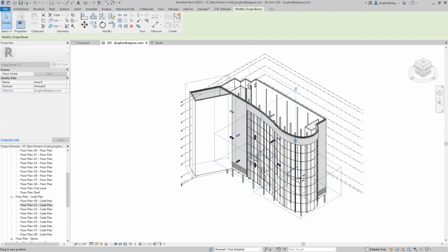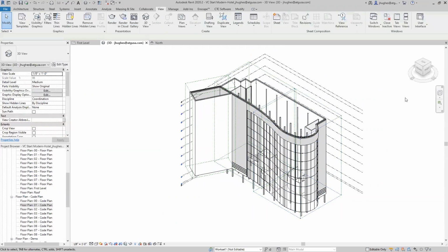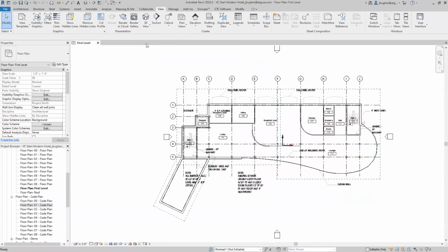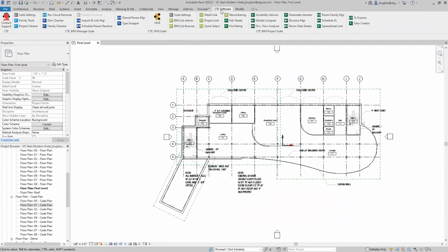Now, what does a scope box do? A scope box helps to align views on multiple floors so that they occur precisely within the same boundaries. It lets you place them so that each floor doesn't have its own different crop boundary. We can actually assign your crop regions to exactly match the scope box. That's one thing it will do for you here. So we've created our scope boxes. We're ready to go back to View Creator now that these are created and double checked here.